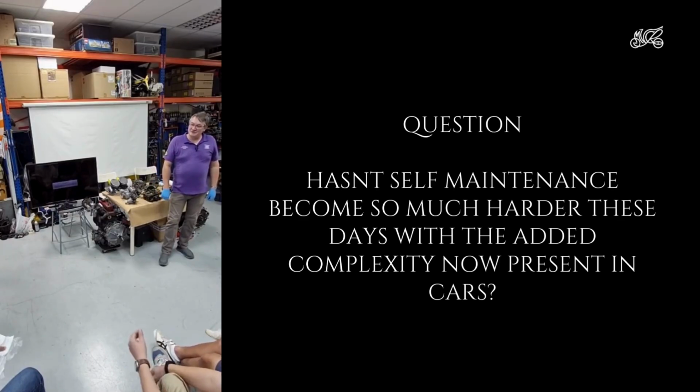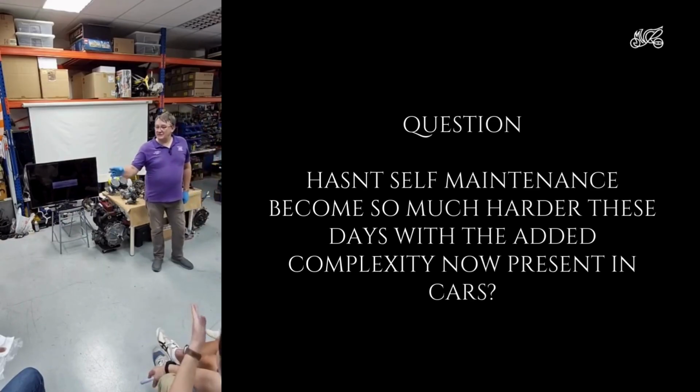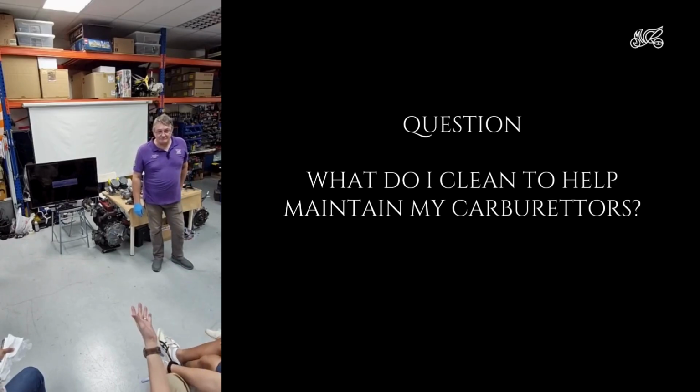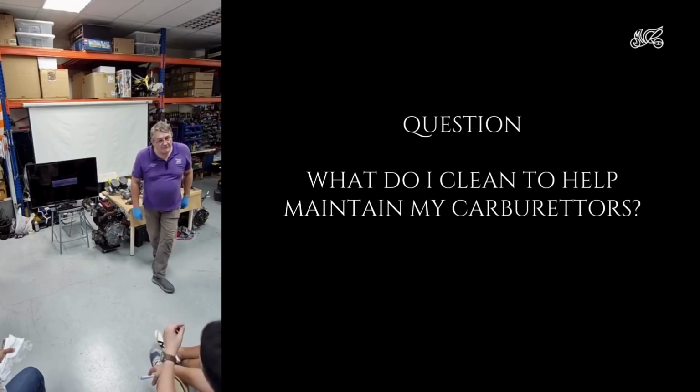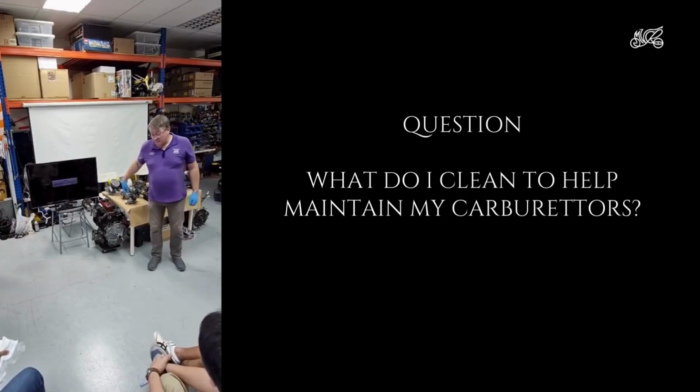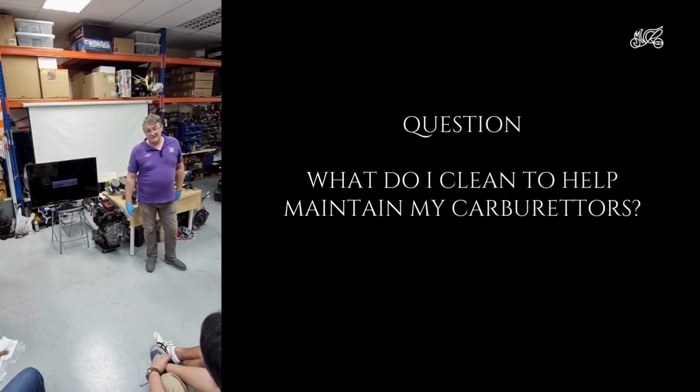we're not going to go into COP, right? So coming back to maybe what you mentioned about cleaning, about the carburetor cleaner. What exactly am I cleaning? Okay, well, you're cleaning the dirt out of the venturi. So carburetor cleaner is normally just a dangerous solvent, a solvent which probably doesn't meet environmental requirements, and you spray it.